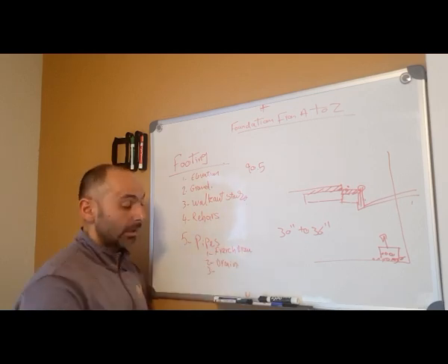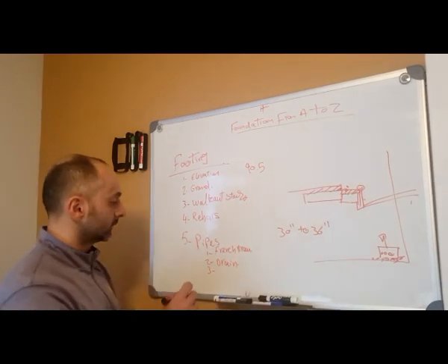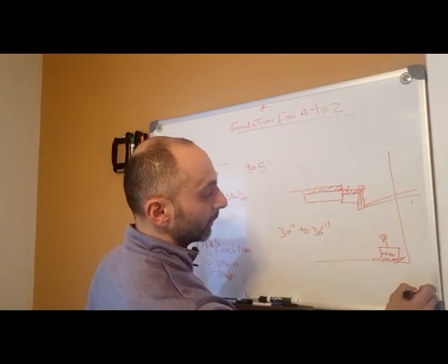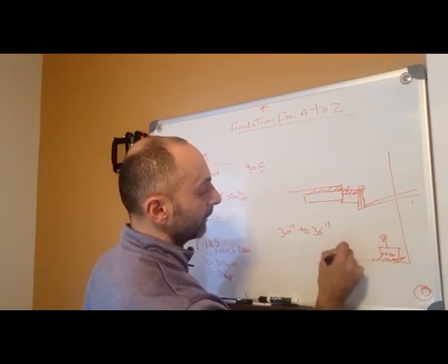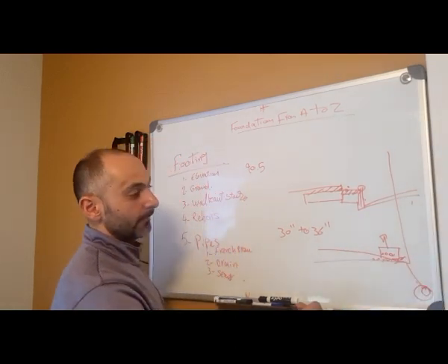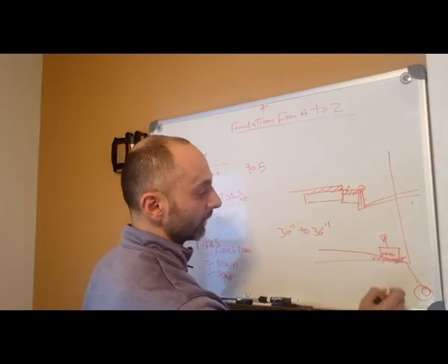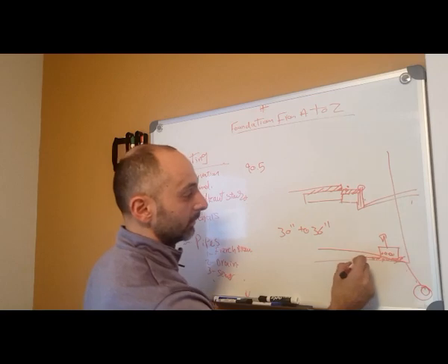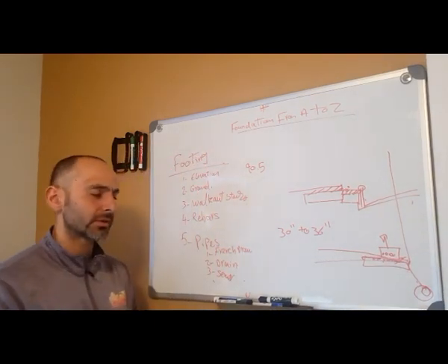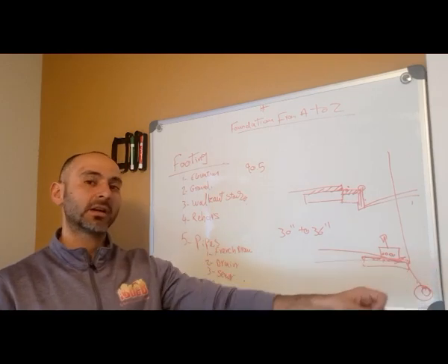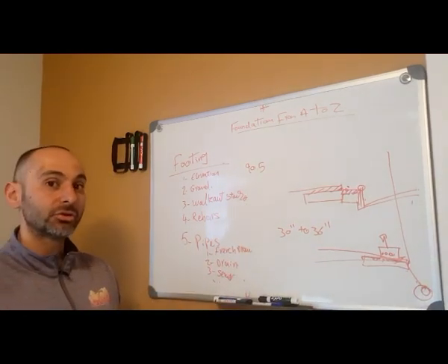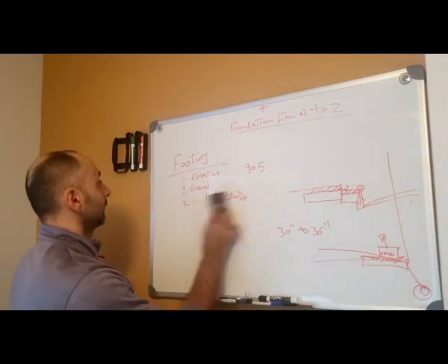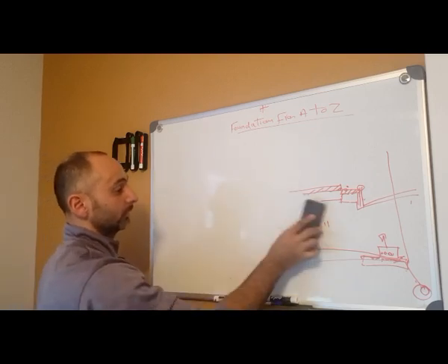Number 6, sewer. If your sewer in the street is lower than the building, it will be an easy hookup. If it's not, don't worry about the sewer. If your sewer on the street is lower, just run usually a 4 inch sleeve, schedule 40, schedule 35, whatever, so you just get to the other side. So once you pour the footing, you don't disturb it, you don't dig under it. Okay, it's all set. From the footing, we're gonna go to the wall.